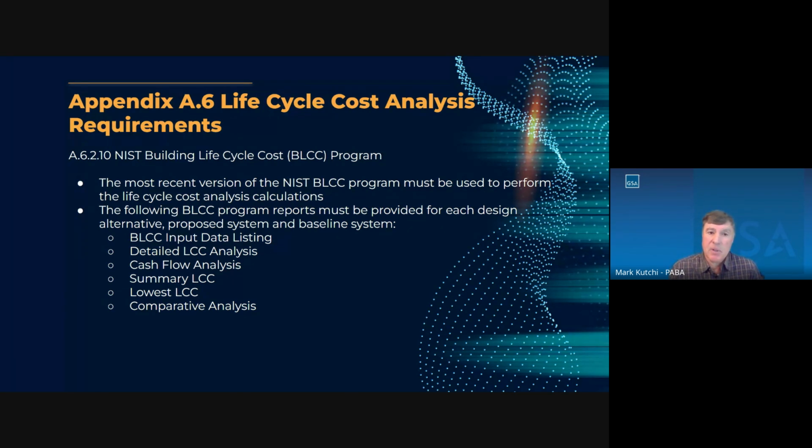The NIST Building Life Cycle Cost Analysis program, the BLCC program, the most recent version, must be used to perform the life cycle cost analysis calculations. And then the following reports should be listed and included in the life cycle cost analysis. One of the most important ones is the BLCC input data listing. That report shows all the input to the life cycle cost analysis, and it's very important to validate those inputs again to make sure that the life cycle cost analysis is correct.